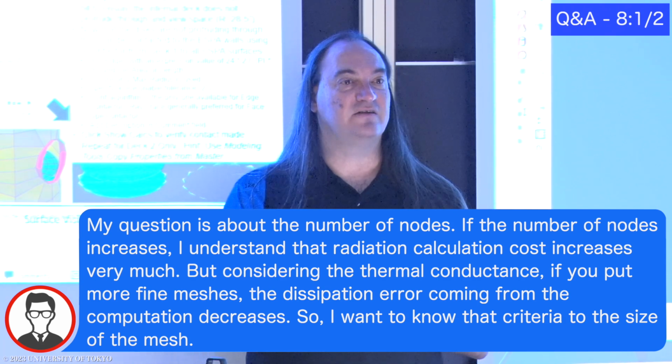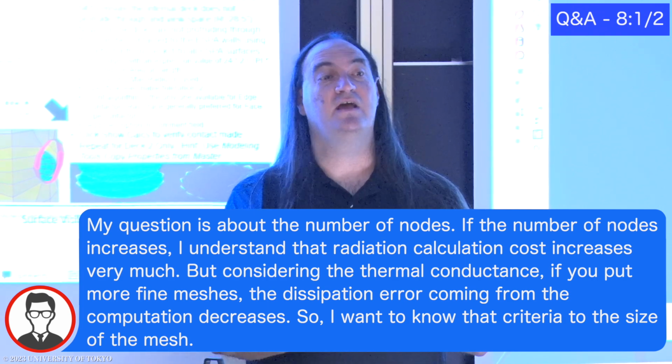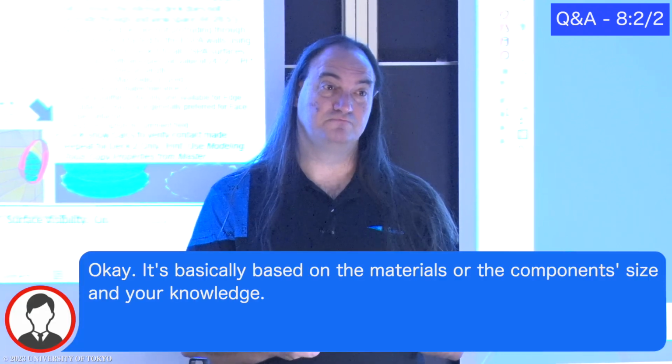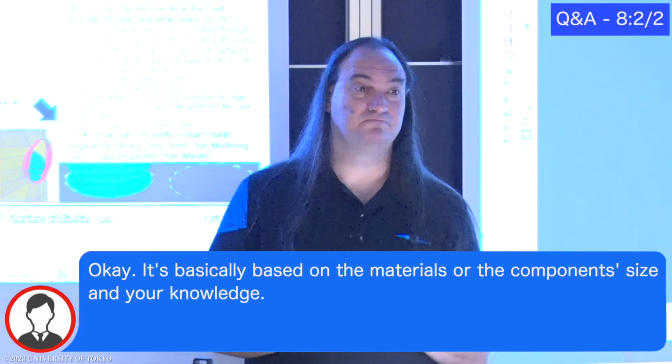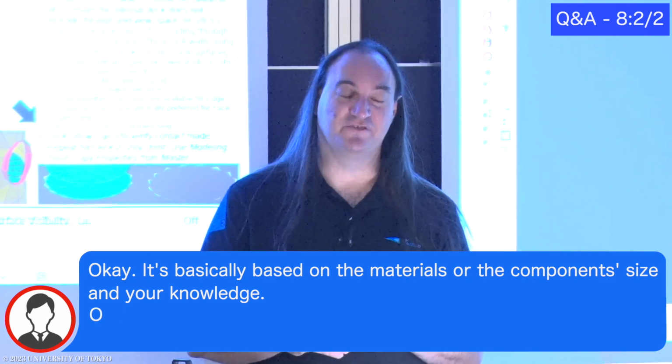Thick, high conductivity surfaces, you need less nodalization. Thin, low conductivity, you want more nodalization. Yes.